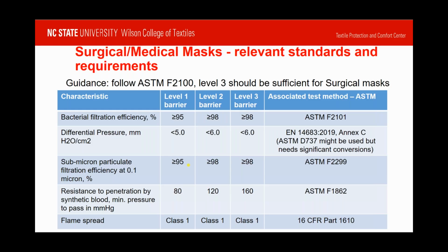Yes, I should defer to our filtration experts, of course, but I think part of it is when you have smaller particles, they will start to behave more like air, and air molecules have a diffusion characteristic to them. So if the airflow is not extremely high, they move more randomly back and forth, the Brownian motion in technical terms, which means they have a higher likelihood of actually hitting a fiber and being captured there. Whereas for larger particles, it's a little more complex than that, so I really refer to last week's webinar on that.